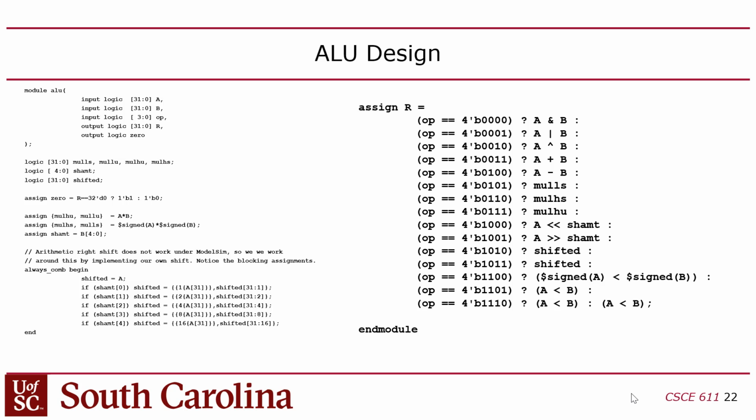That makes sense? But you don't have to worry too much about this because we just give you the code. Also, the shifter was kind of strange. Verilog has a shift operator, but we couldn't make it work. I don't remember the exact problem, but in this case, we had to manually implement the right shift. We had to do this logarithmic concatenate.